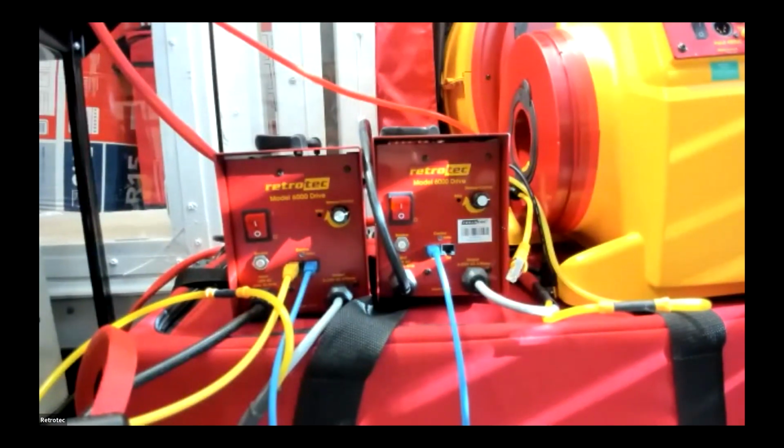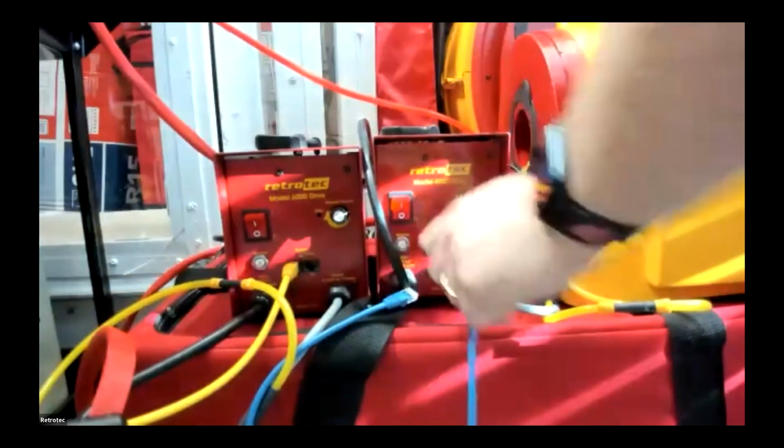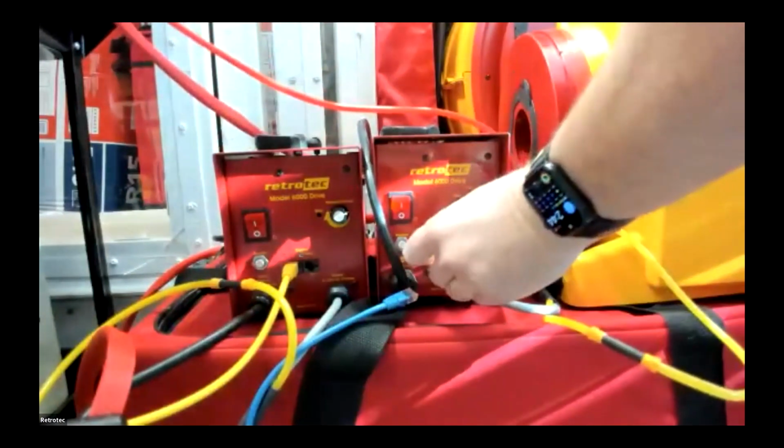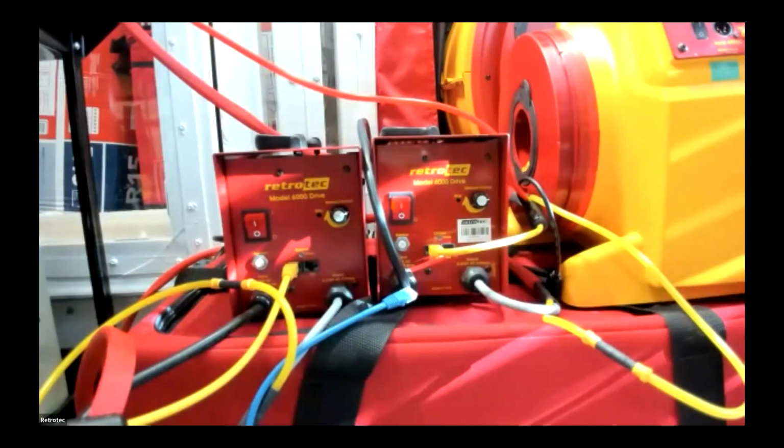The other way that we would have things set up is independent control. That's if you're doing a guarded test or a neutralization test on maybe duplex or apartment buildings. Instead of daisy chaining the fans together, you would have each separate manometer connected to the fan. Then in the software, you want to make sure that you have that selected. There's the option of common control and individual control. The common control is one gauge telling them all what to do.